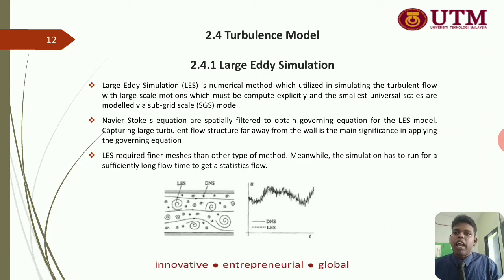Turbulence model. Large eddy simulation. Large eddy simulation is a numerical method which is utilized in simulating the turbulent flow with large scale motion, which must be computed explicitly, and the smallest universal scale are modeled via subgrid scale SGS model. Navier-Stokes equations are partially filtered to obtain governing equation for the LES model. LES requires finer mesh than other type of method. Meanwhile, the simulation has to run for a sufficiently long flow time to get a statistical flow.